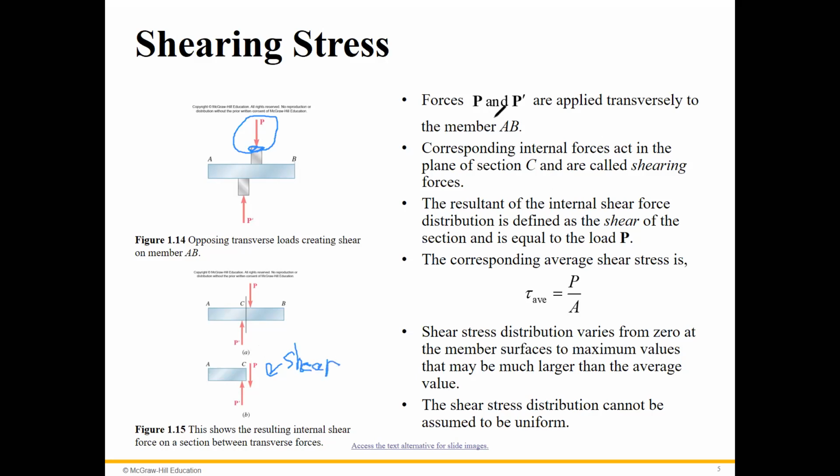Yeah, because we want to talk about member AB. But you are right. If somebody said we want to focus on this member, for example member CD, then this force plays the role of normal. Actually, your question is very good, because next week I want to solve some problems that are very complicated. We have one single force, but for one element it plays the role of normal, for another element the role of shear, and for some element the role of bearing stress. I want to talk about bearing stress also later.